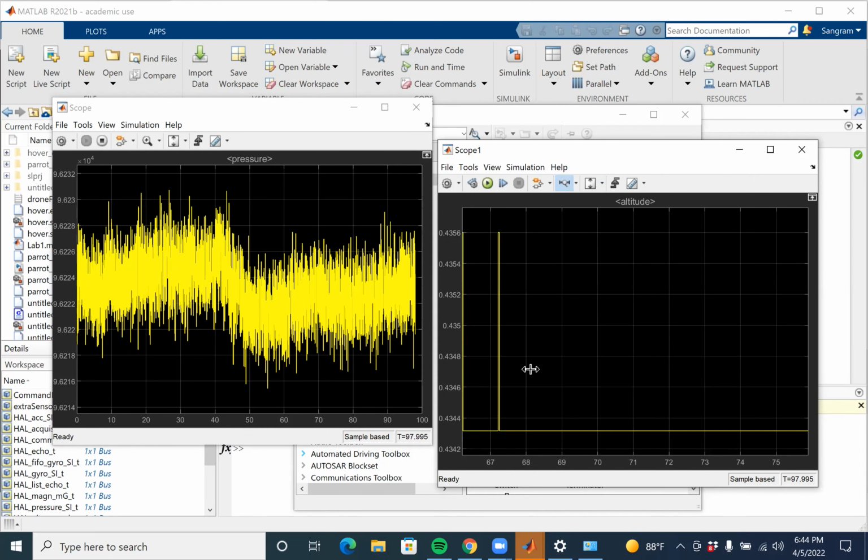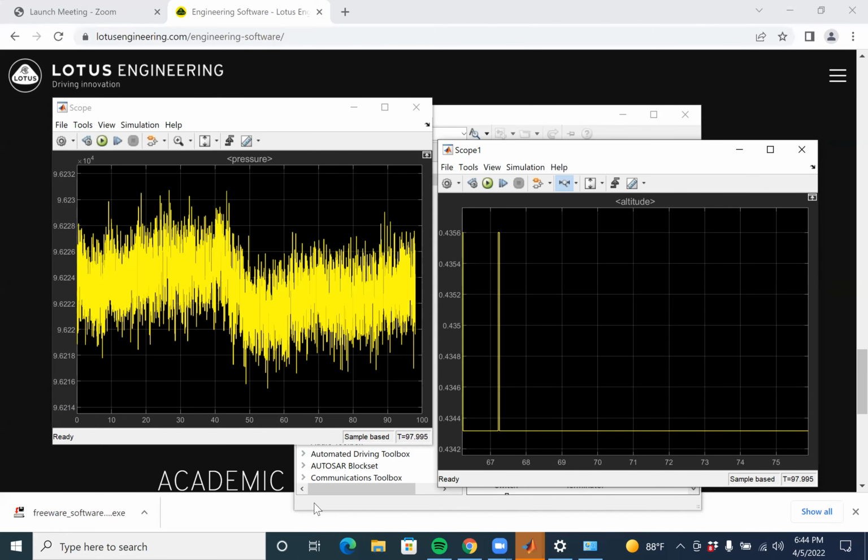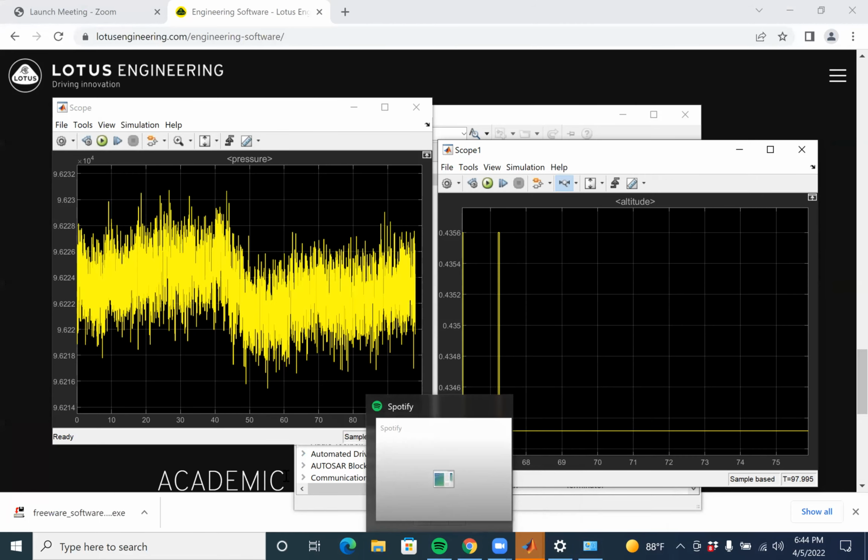So as you can see, this value changes, and clearly the pressure value that you are getting is kind of noisy. So you want to run this pressure value through a low pass filter. And the easiest way to do that, so you got your moving average working, right? Finally.